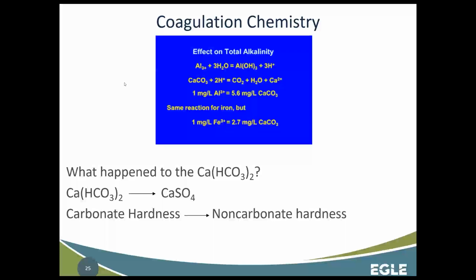And why are we looking at it from that perspective? It's because ultimately we're trying to achieve charge neutralization. The element that's doing the heavy lifting in these compounds is this trivalent metal, aluminum or iron. That's really what's important for our dosing, to make sure that we get enough of these ions introduced to the source water so that we can neutralize those particles. So if we get caught up looking at the weight of alum or the weight of ferric, we always need to keep in mind that our goal here is to get enough of these ions into the water to neutralize the charges.